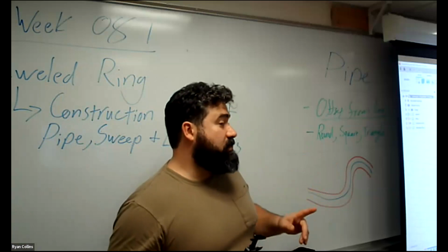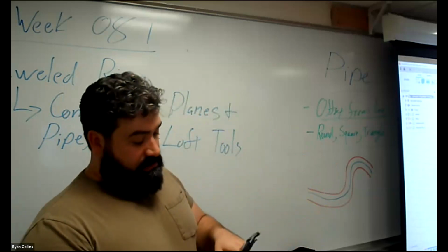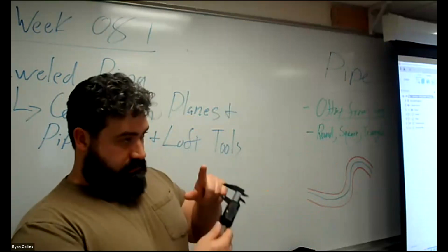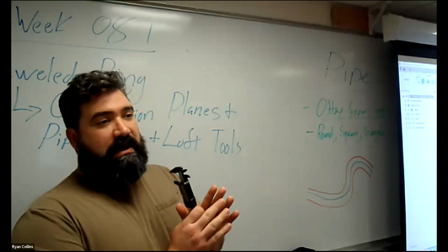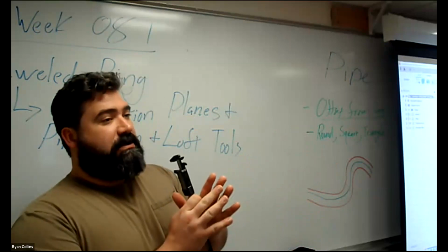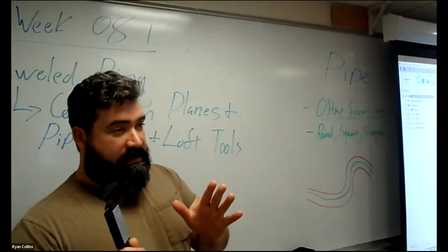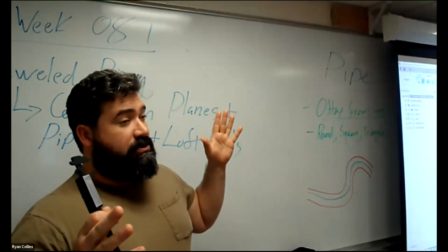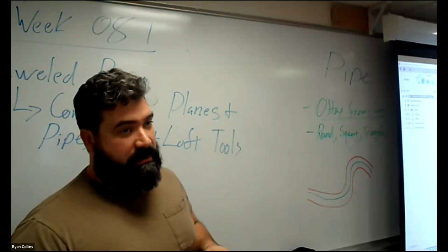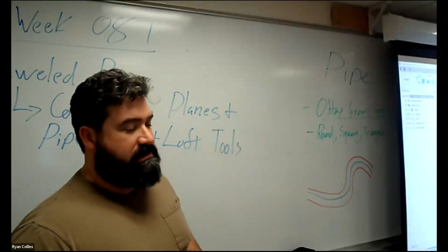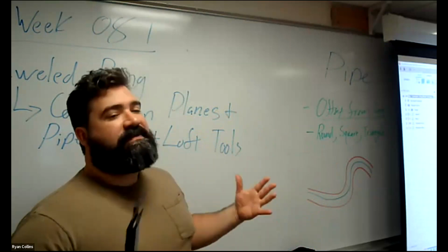So if you use a pipe tool around a 20 millimeter ring size or diameter size, and make it 2 millimeters wide, it's going to go 1 on the inside, 1 on the outside. So you're going to shrink the diameter of your circle essentially by 2 millimeters. So play with it. You might have to scale that stuff up.